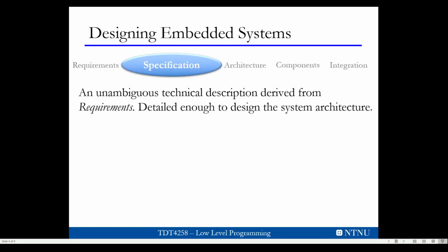Now the next step is to derive specifications, and these are the unambiguous technical descriptions that we need to provide the system designer or the engineer. Let's take a look at what the specifications can be. For our example of GPS moving map, one of the requirements was that it should fit on the palm. But the size of the palm can be ambiguous. When we derive specifications, we have to give an unambiguous description. In this case, it could be 2 by 4 inches. Again, the requirement of 8 hours on batteries could translate to a maximum power consumption of 100 milliwatts, and so on.